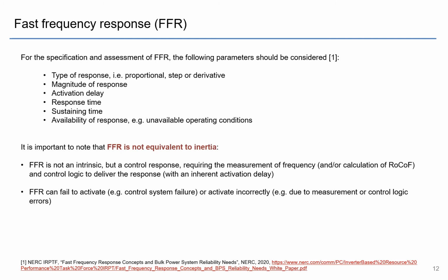It's also important to note that FFR is not actually equivalent to inertia. FFR is not an intrinsic response, but it's a control response. So you need a control system to create the FFR response, requiring the measurement of frequency and/or calculation of the RoCoF and some logic to deliver that response with some inherent activation delay. And one of the main problems is that FFR can actually fail. So you might have a control system failure, or it can activate incorrectly due to some measurement or control logic error.